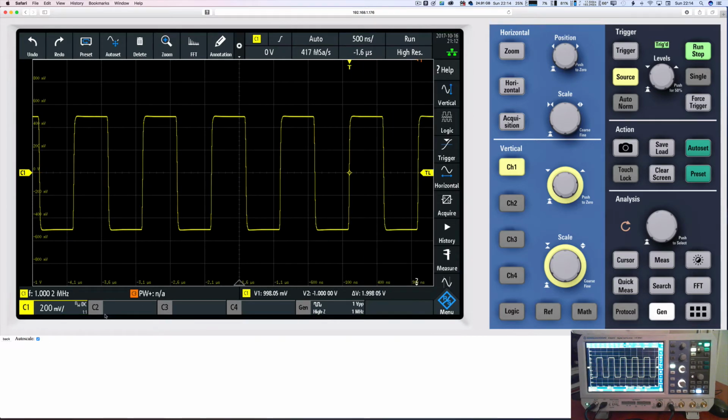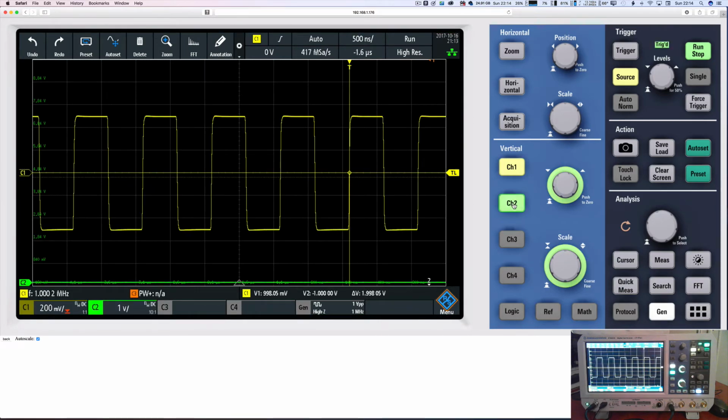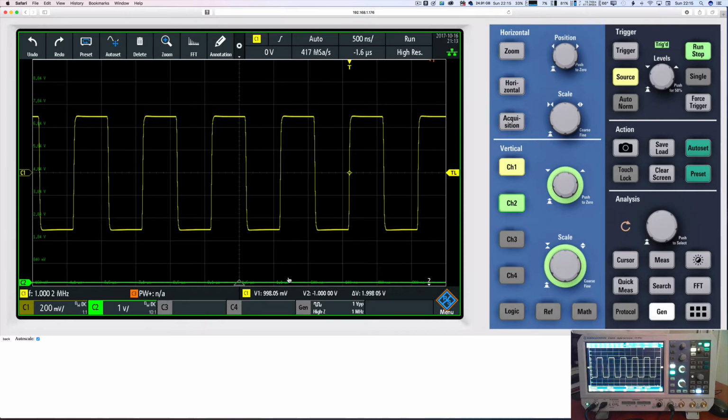So those are each of your probe settings, channel settings and probe settings. So this is the 200 millivolts vertical sensitivity, bandwidth limited, DC coupled with 1 to 1. It's nice that you can see it all in one go, and you'd see the same if I switch on channel 2 here. Green light will come on the scope. It's come on here.